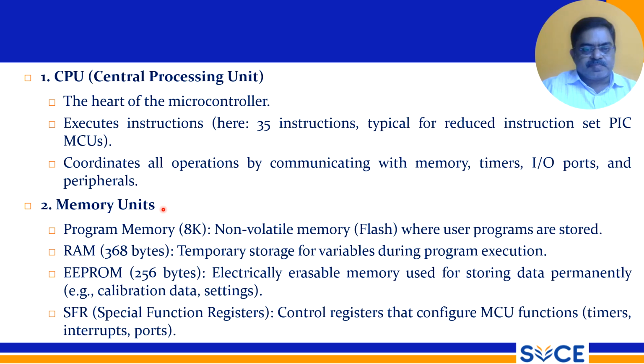Memory units. Program memory is 8K, non-volatile flash memory, where user programs are normally stored. RAM is 368 bytes, temporary storage for variables during program execution. EEPROM is 256 bytes.